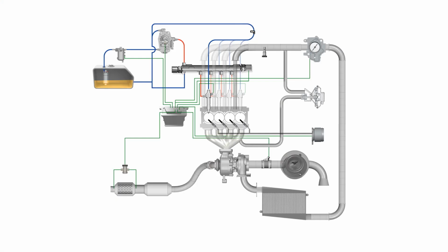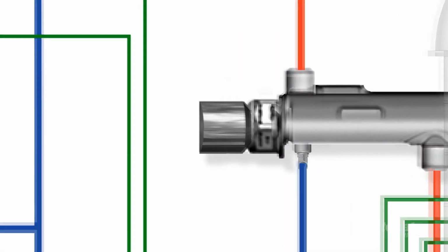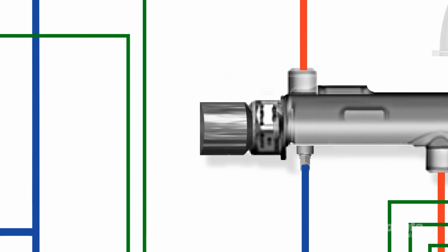If the pressure was at its maximum and the engine was idling, the injector wouldn't be open for very long to deliver the amount of fuel required. This would be hard to control. By reducing the pressure at lower engine speeds, it gives us a longer injection duration, and this is much easier to control. Some CRD engines may have a pressure limiting valve in the fuel rail.